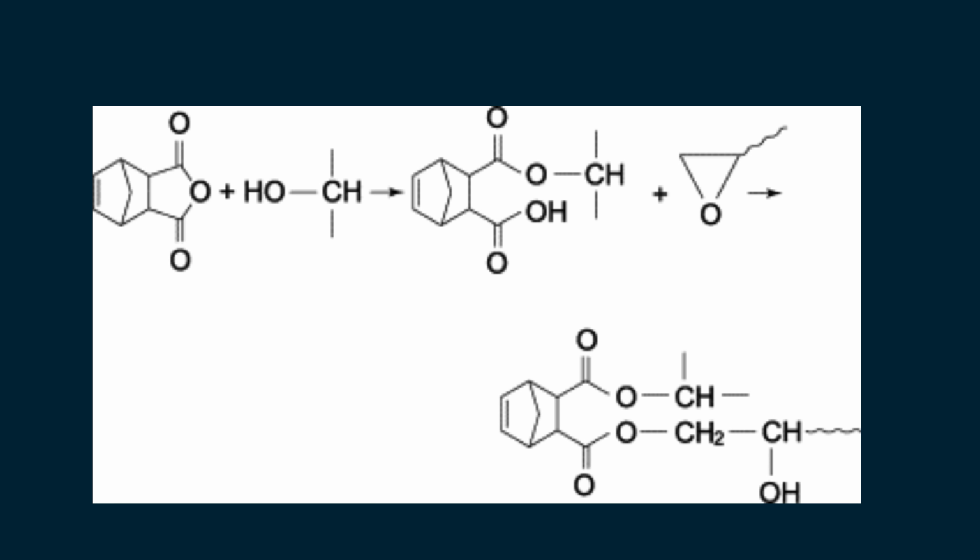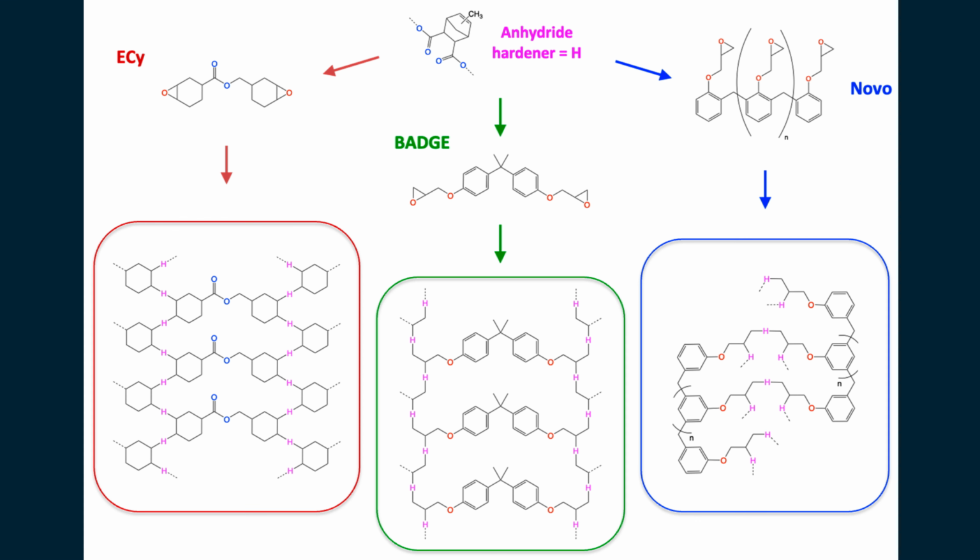It is a liquid with a viscosity of around 200 cP at room temperature and dissolves readily in epoxy resins. Typical formulations use 60 to 90 pph NMA with DGEBA epoxy resins. Without catalysts, the mixture may remain workable for months. When accelerators such as DMP-30 are added, working life decreases to several days. By adjusting curing conditions and composition, a wide range of mechanical and thermal properties can be achieved.